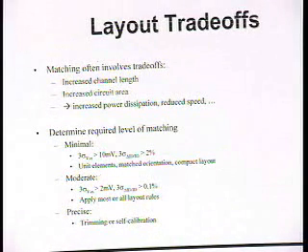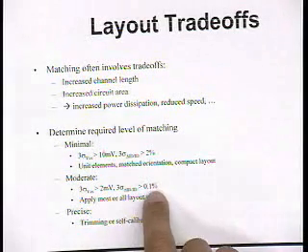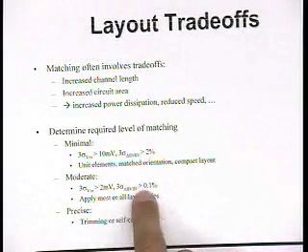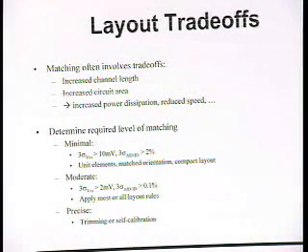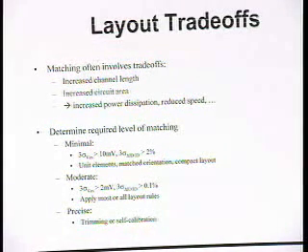If you need better than that, then almost all the techniques that we're going to talk about have to be applied very, very judiciously to get down to 3 sigma of 2 millivolts and current matching of 0.1%. If you need more than this, you're going to have to pay. You're going to have to do calibration, either post-process or on-chip calibration, or use some kind of tricks and techniques.